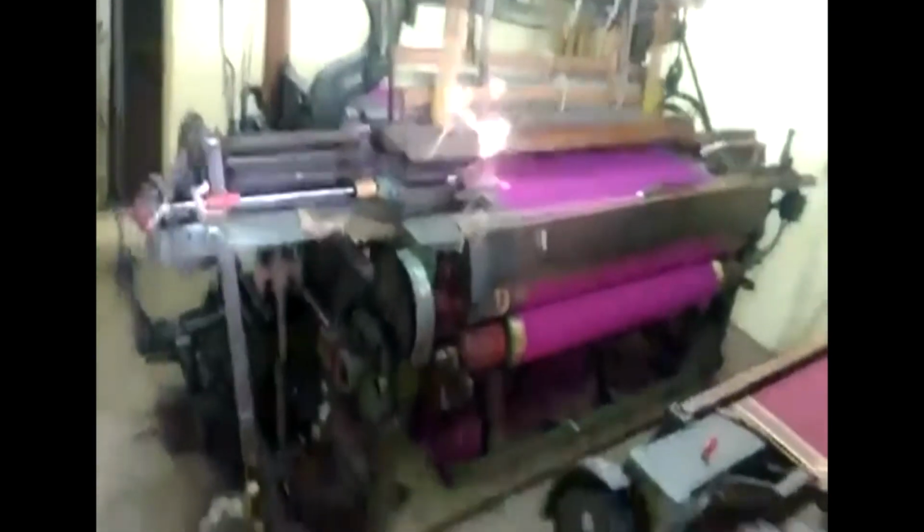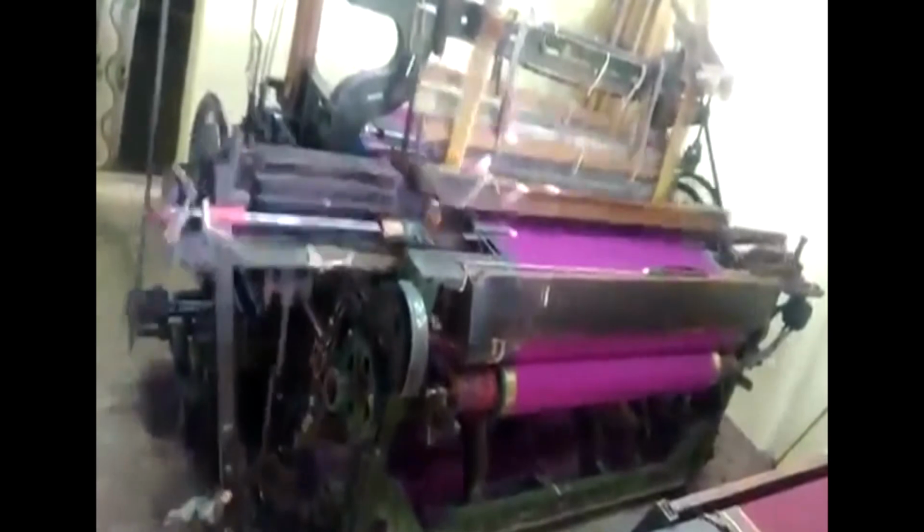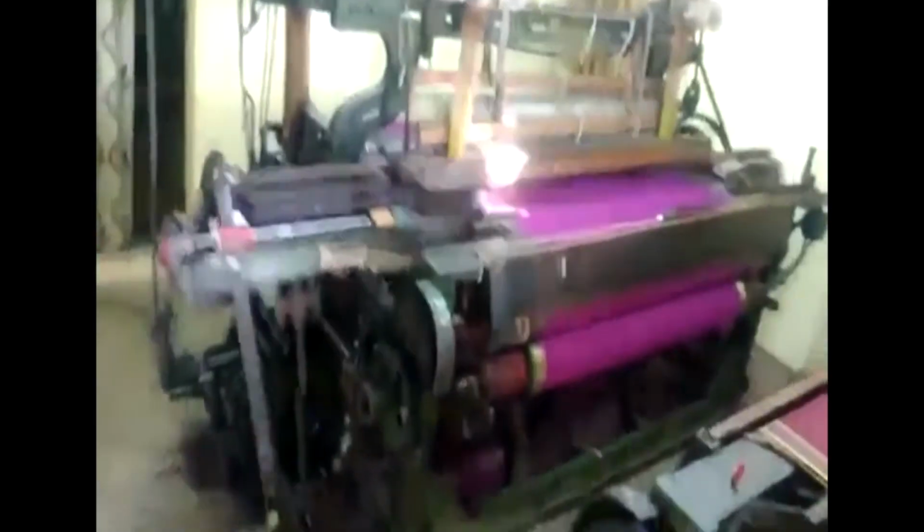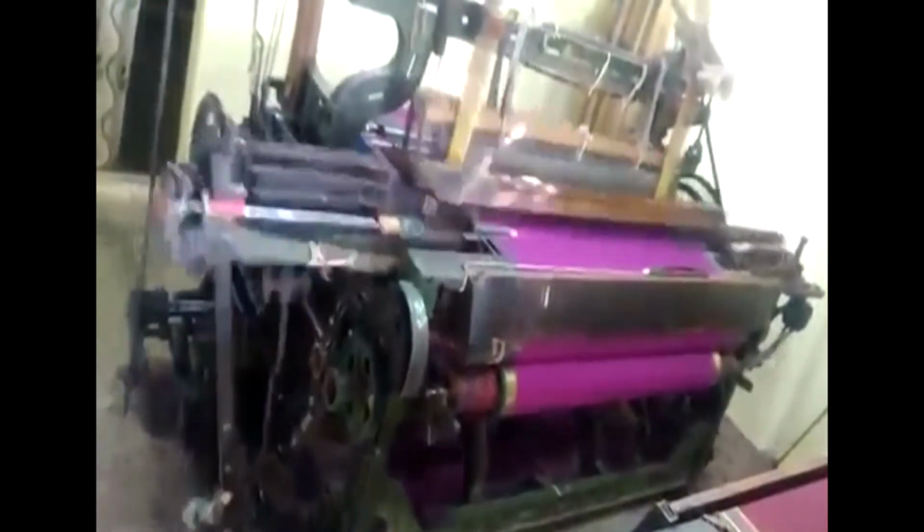This shuttle has to be accelerated rapidly at the start of the pick cycle, and second, it has to be decelerated, that is, it has to be stopped at the other end. Now this stopping has to be abrupt. This pushing from one end and stopping at the other end requires a lot of power. Due to this motion of the loom, a lot of energy is required, and it also requires some amount of time. This process causes heavy noise. It also causes shock and consumes considerable energy.